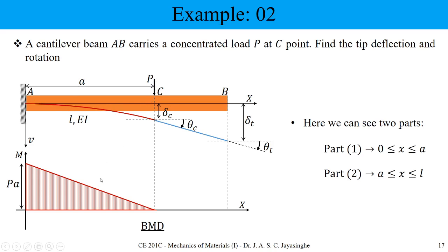Okay, so if you're going to develop the bending moment diagram, now I think you know this one. This until to here is like a cantilever. After that we cannot see any bending moment. Yes, you're correct. So actually in here we need to work with two bending moment values. We have a bending moment variation like this diagram, and here the bending moment is actually 0.